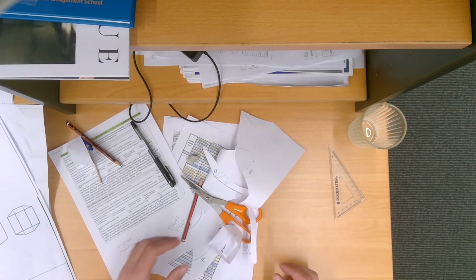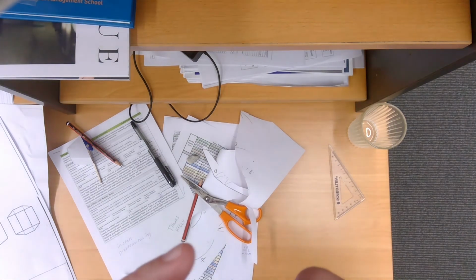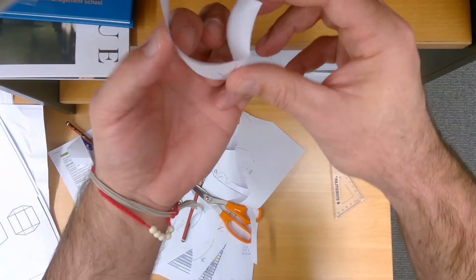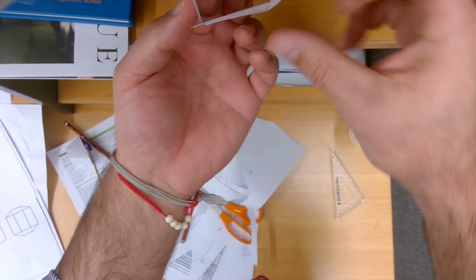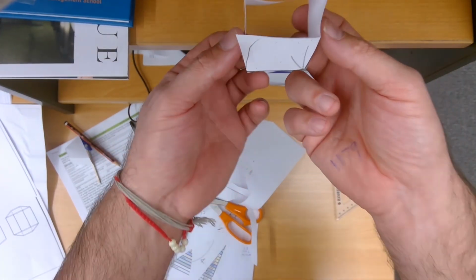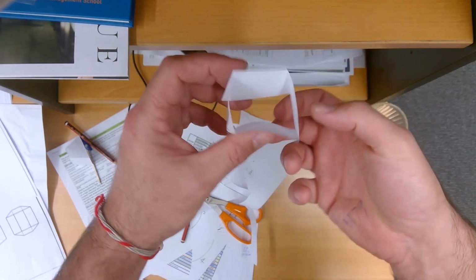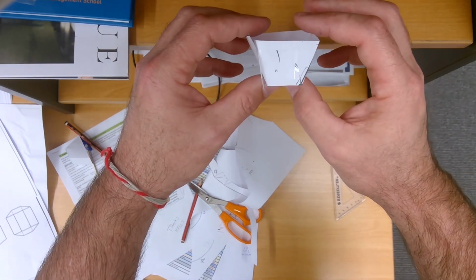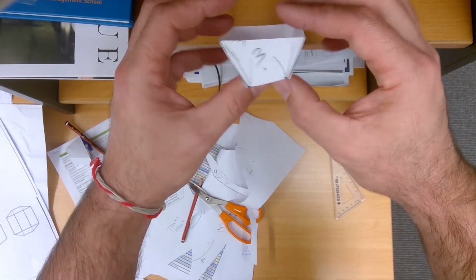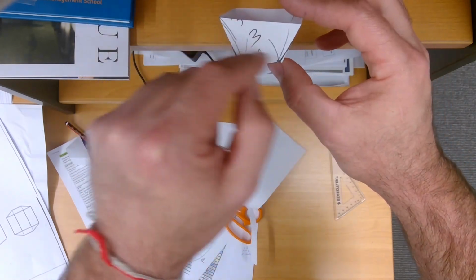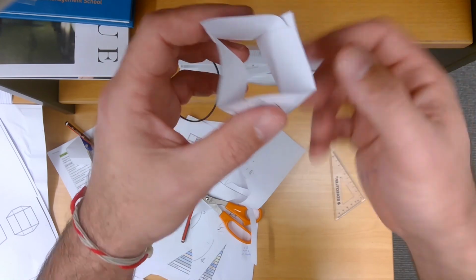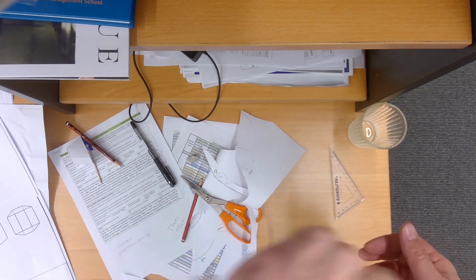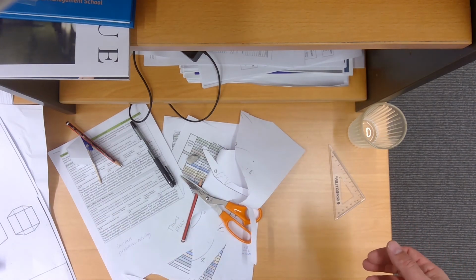Now, obviously, some inaccuracy has crept into this whole situation, but you can see from the bottom we have a rectangle, and from the top we have what approximates a square, and that is our side view. So we've actually stuffed up a little bit here because of inaccuracies in swinging and whatnot, but that's how you do a transition piece, rectangle to square. Follow the video, practice, you will get better at it.